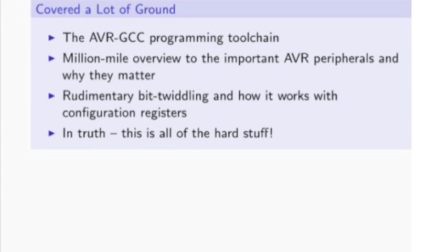And so when you do digital write next time, think about those 45 cycles that it's taking to do it, and think to yourself, yeah, you know, maybe I could just write port B equals something, something. And heck, if I even wrote a macro, I could do it, and so it would be readable. And then it would go in one cycle. So I could toggle that pin 40-something times faster. Yeah, if that doesn't inspire you, I don't know what will.